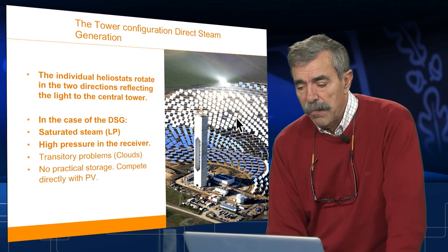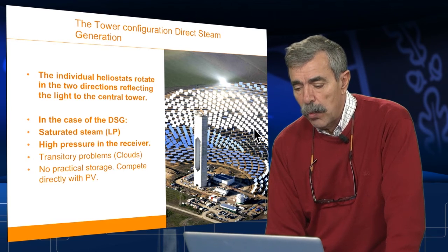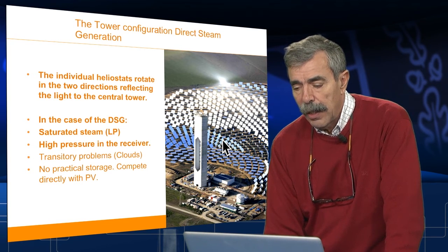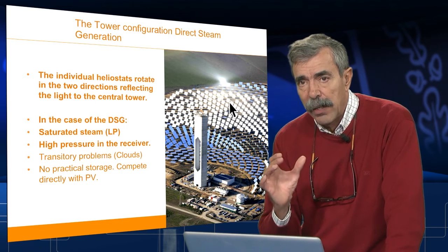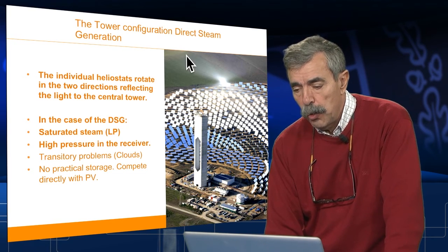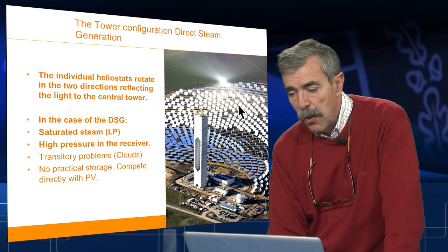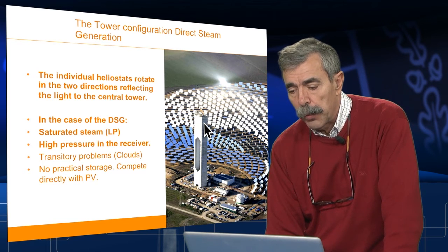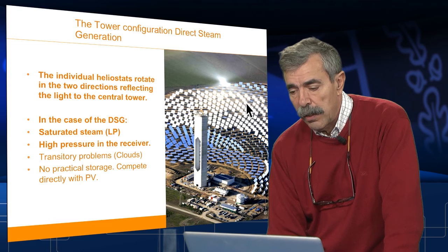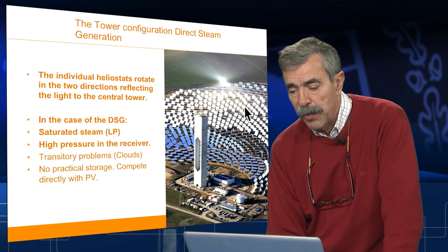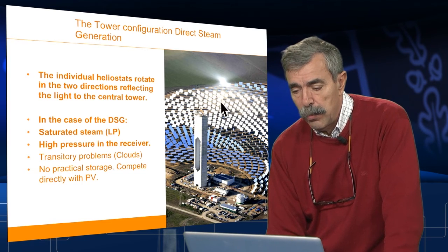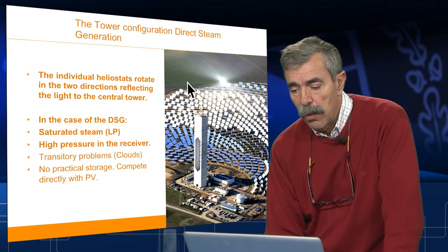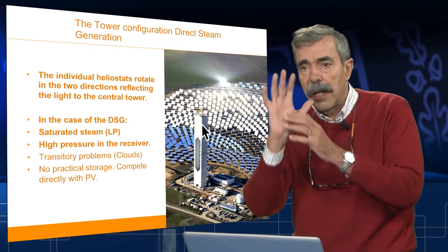I want to emphasize that every individual heliostat in the solar field has to adopt a different bidirectional angle to reflect the light of the sun, aiming at a certain point. Since the relative position of the heliostat versus the target differs from one heliostat to any other, the angle to obtain the light concentration on the target also has to be different.